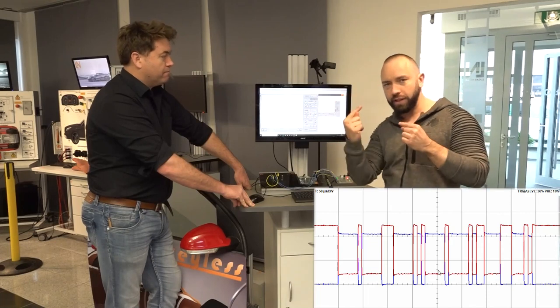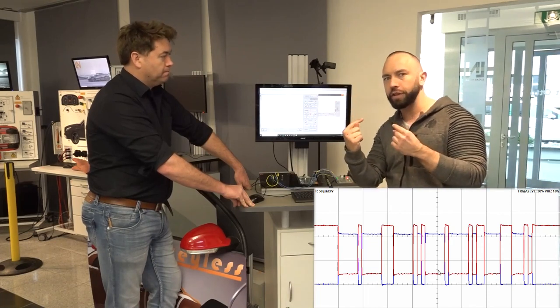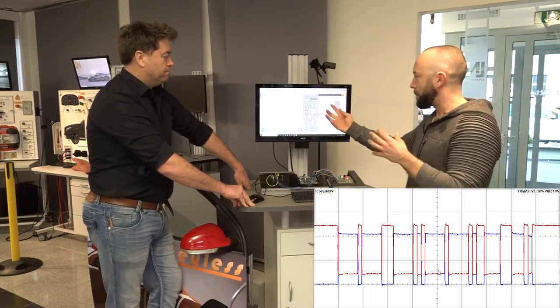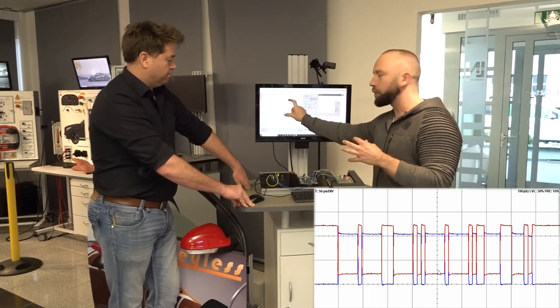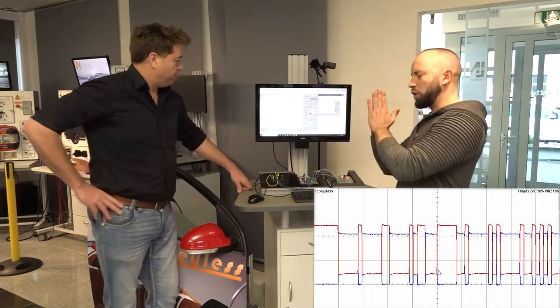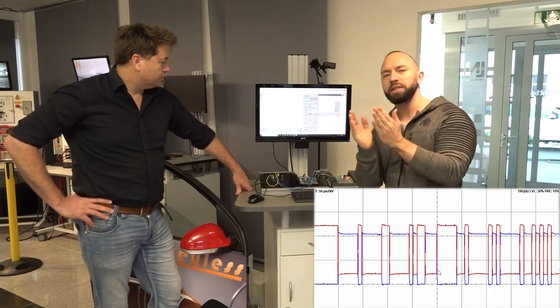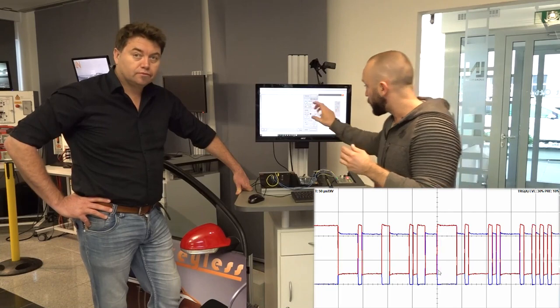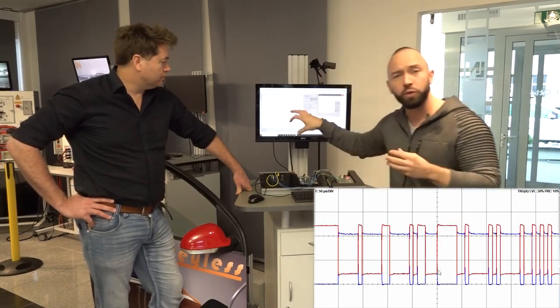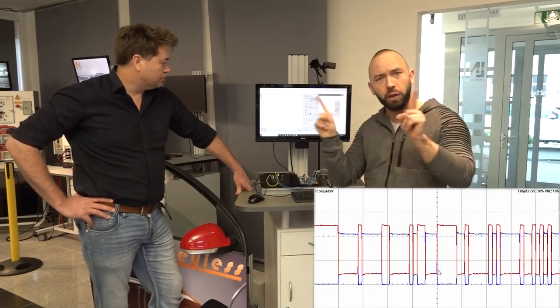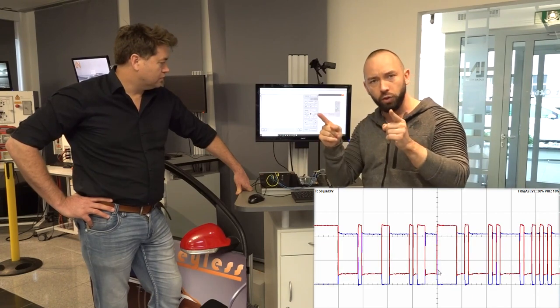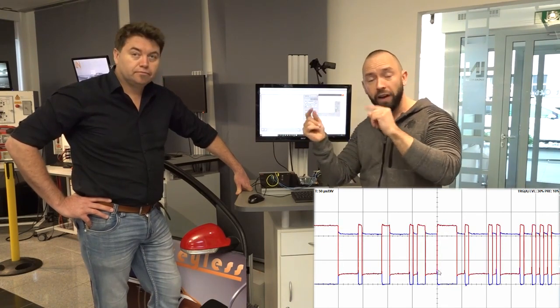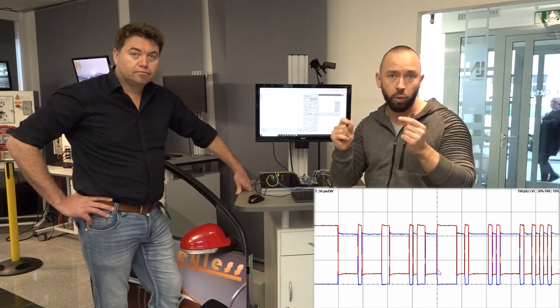And maybe just one word for the time division. You really have to see that you choose the right time division, as you see now you have a different view on the signal. When everything is too close, you see there is a signal, but basically you won't see what will change there. And when you zoom more into it, then you have the chance really to see what's happening there. So always make sure that you find the right time and the right voltage division for your signal, what you want to measure.